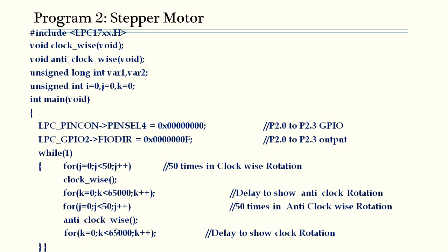So for 360 degrees with the step angle of 1.8 degrees, how many steps are required? You require 200 steps, of which 4 steps are being generated in the clockwise as well as in the anti-clockwise function. Once a clockwise is called, it will generate 4 steps, and hence we require this function to be called 50 times. So 50 into 4 will generate 200 steps.